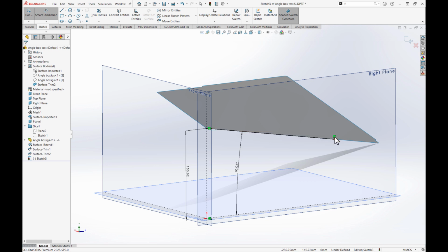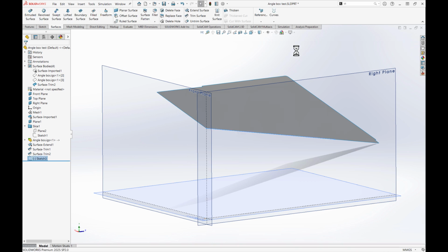And as I've just dragged that line, you can see, be very careful because it's just automatically added a coincident relation back in. So I'm going to delete that again. So you don't want any kind of remaining dimensions that relate this thing directly back to the import. We want to be in control of its dimensions. So I'm going to accept this sketch,